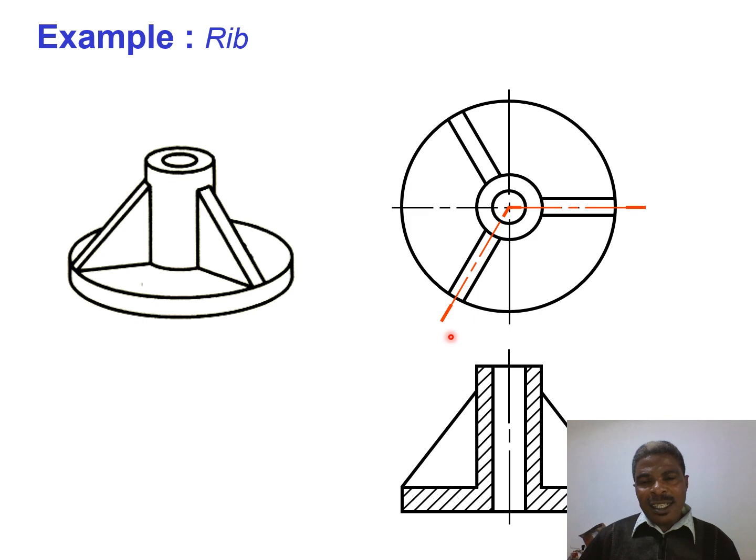So in the aligned section, you simply indicate this thickness of the layer without touching this part of it here. This is not indicated. However, the cutting plane passes through this, then comes at this point. But this is a supporting material to the standing cylinder of this part, so we do not indicate the hatching lines. That's why you can see here. You should be aware of this nature of the material placed here for the purpose of supporting the standing material.